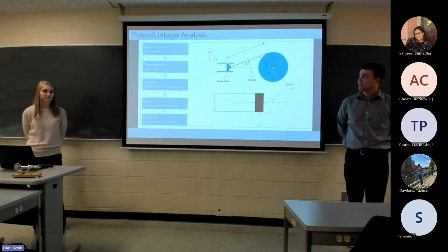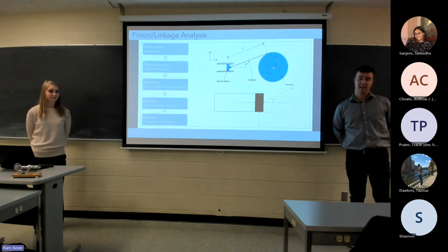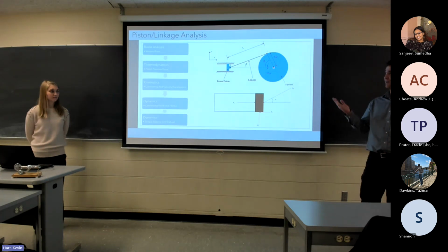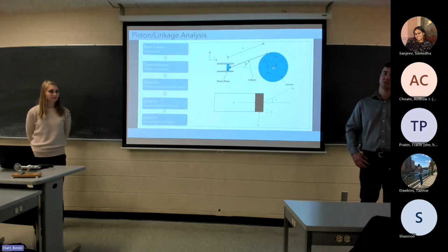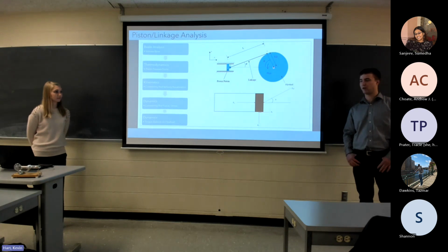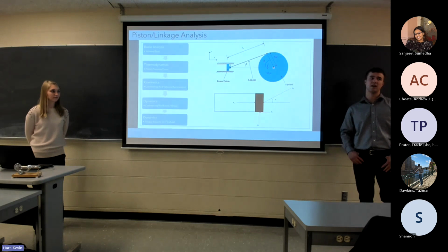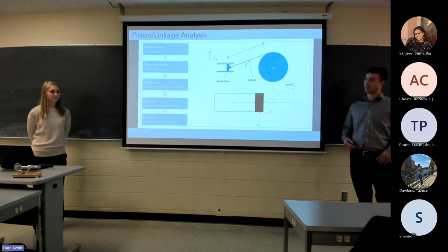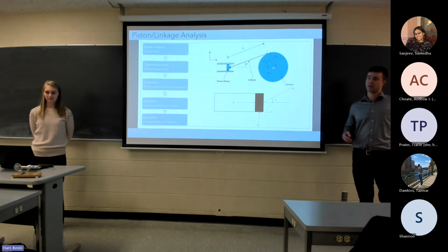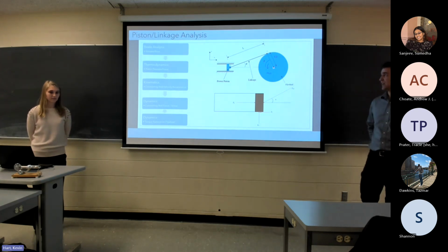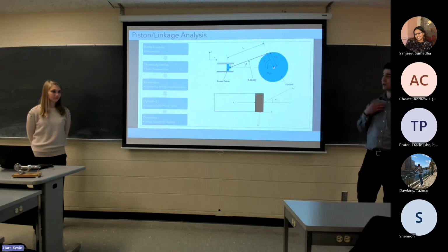So then we dove into the analysis, and at the beginning, we did not know where to start until we found Mr. William Beale. For those of you who don't know, he did extensive research on Stirling engines, and he came up with a formula that relates the volume and the bore of the power piston to the thermal reservoir temperatures. So this is a perfect starting place for us, and we used his equation and got a volume and bore.